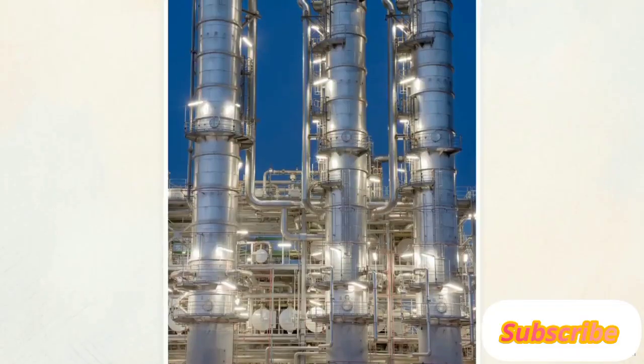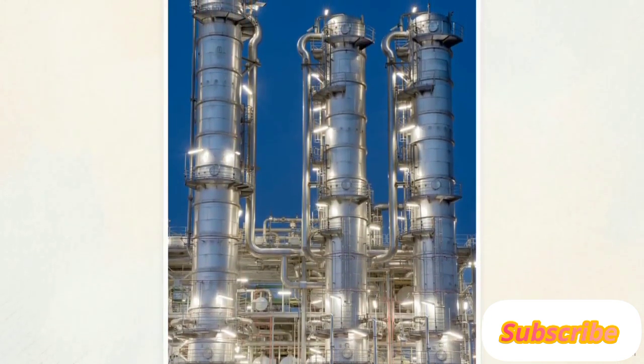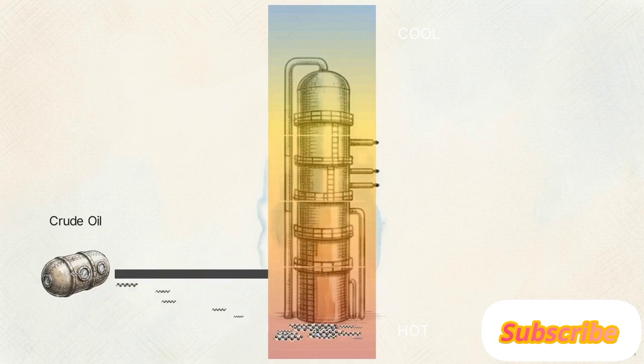The first stage, separation, occurs within these distillation towers. It relies on intense heat applied by a furnace to begin the sorting process. Inside the column, a strict temperature gradient, hottest at the base, coolest at the top, forces molecules to separate by boiling point. Heavy, compact fractions remain liquids, pooling at the bottom. Lighter fractions evaporate, rising through the gradient until condensing in cooler upper tiers for extraction.